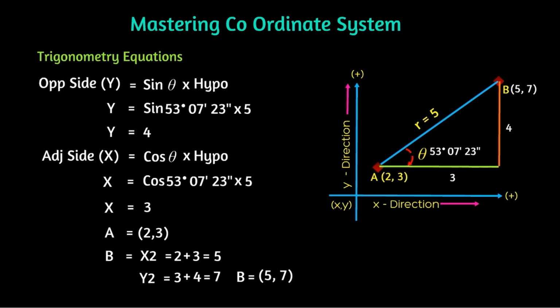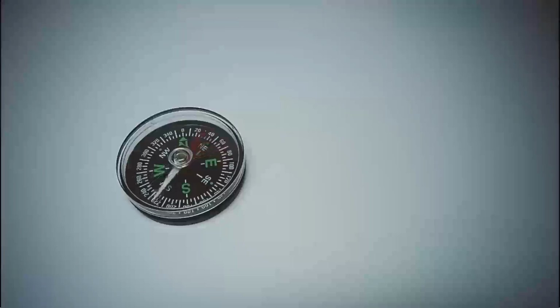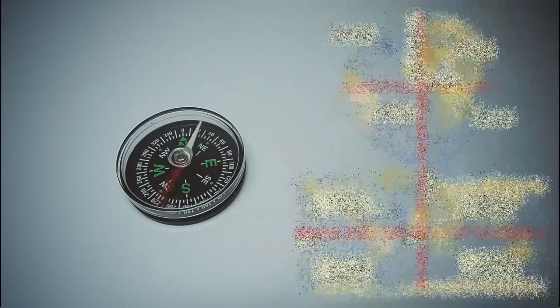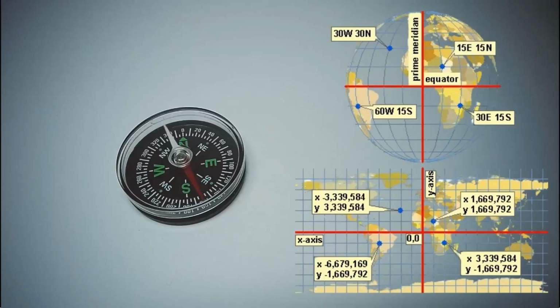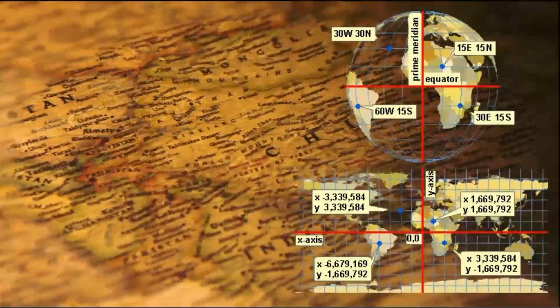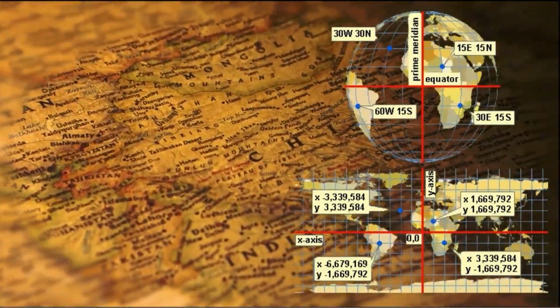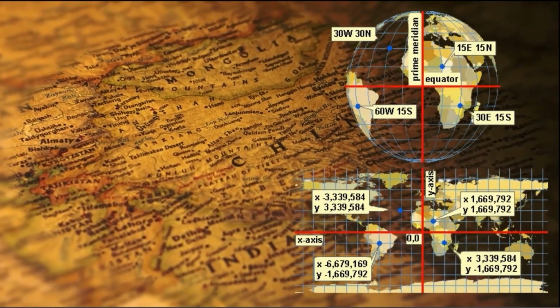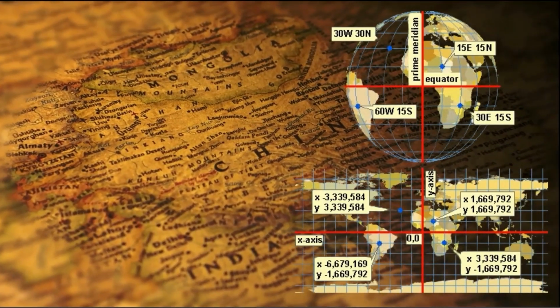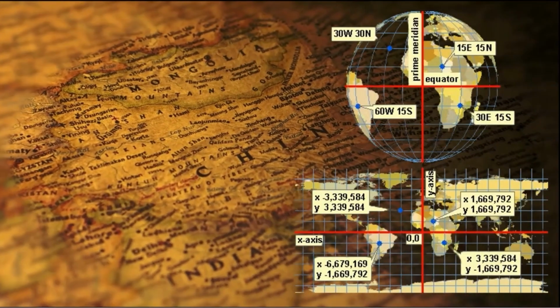Now that we understand coordinates, let's see how surveyors measure them in the real world. Understanding northing and easting in surveying and its applications. In real-world land surveys, we don't just use X and Y coordinates. Instead, we use a special system called northing and easting to define locations on the Earth's surface. It is also called latitude and departure. Northing and easting coordinates are crucial in land surveying, engineering, and mapping. They are widely used in computer-aided design (CAD) software, town planning departments, and topographic surveys.